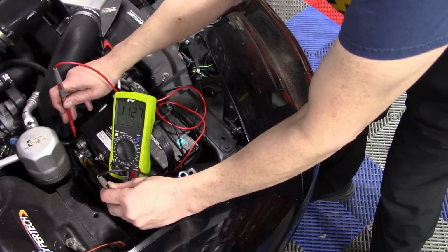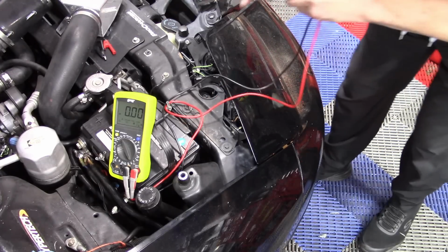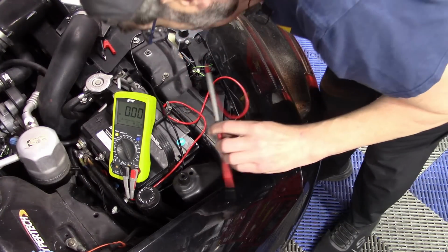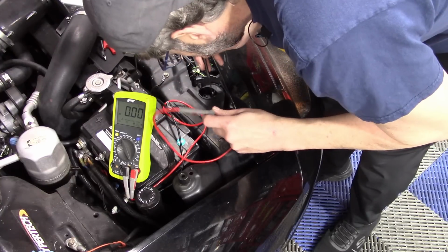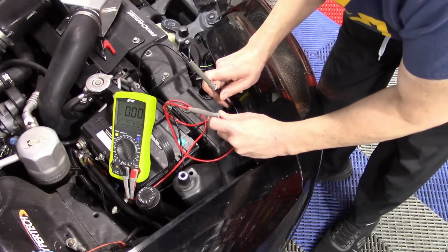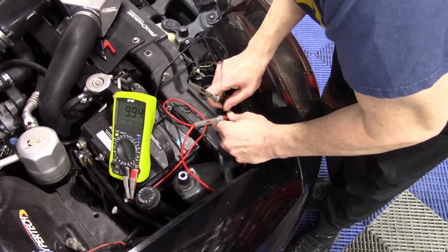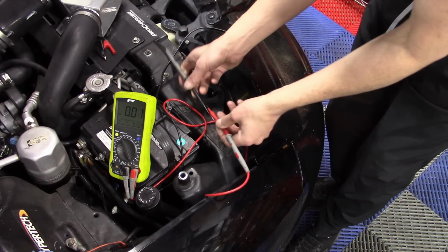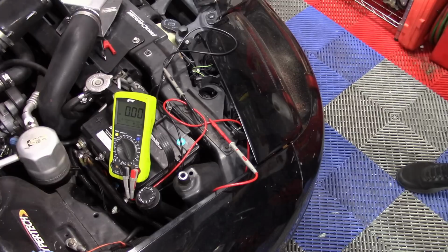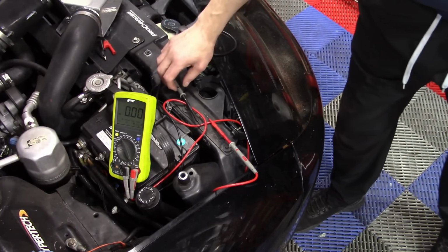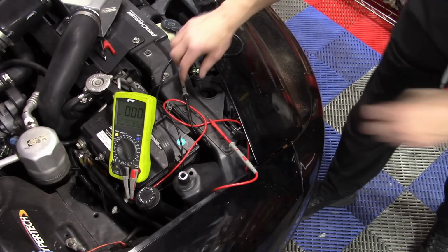All right, so my battery is a little bit weak, but the problem is that we measured 10 something at this bulb, which means we're losing some voltage somewhere. We had 11.27 at the battery, we're reading just about 10, so we've got a little over a volt of drop from our battery voltage to where we're measuring at our light bulb. Where are we losing that volt?